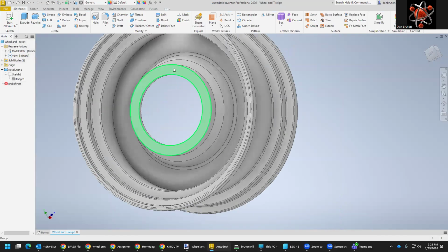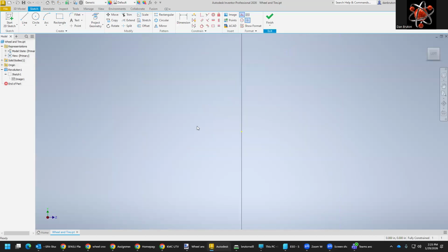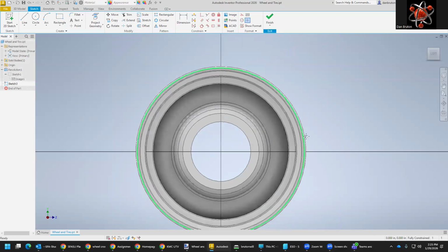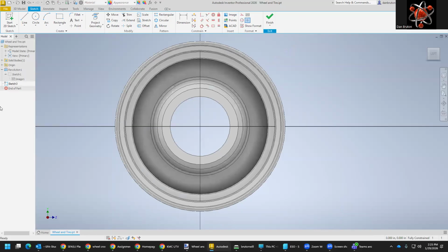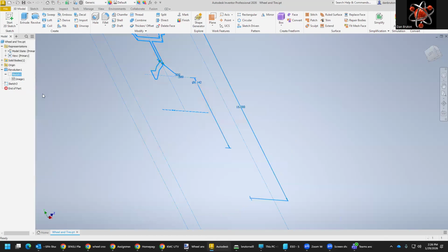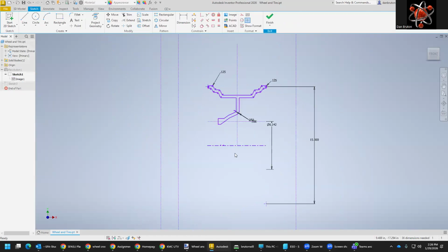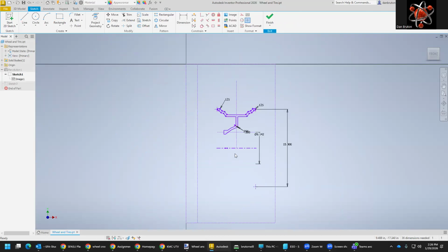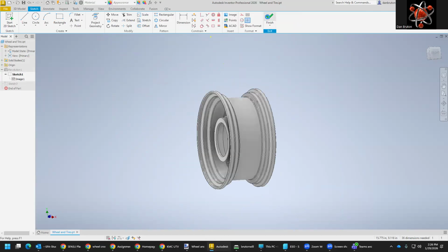But now we can go back and right click on this surface here, new sketch. And you know what? Let's go back. Let's finish that right there. Let's go back on this one and say edit sketch. Can we move this whole thing to the origin? You know what? It would probably distort things. If we try to move this over to the origin, it would probably distort all this because you can see it's not fully defined.